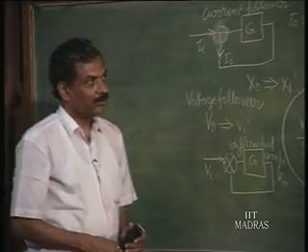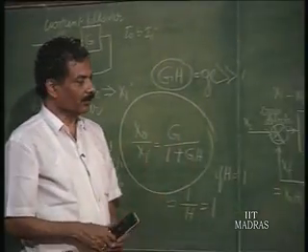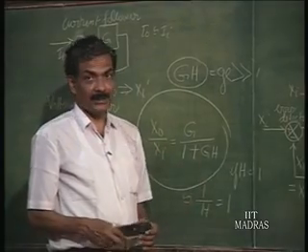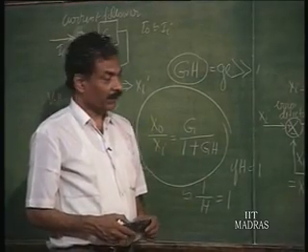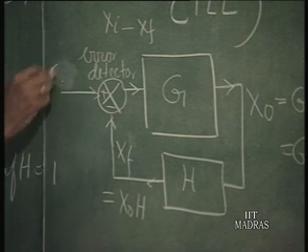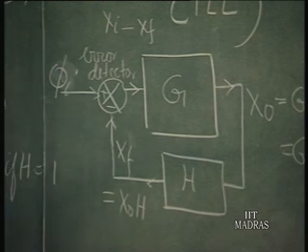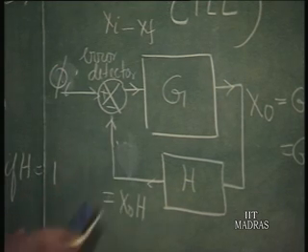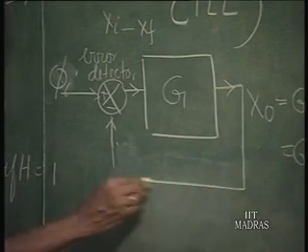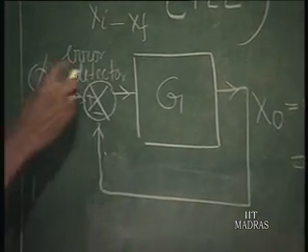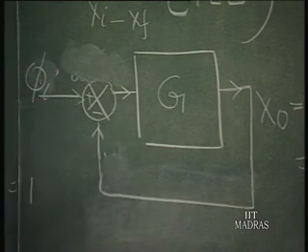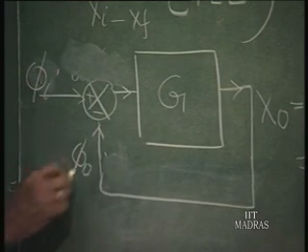Now, when we go to phase lock loop, neither voltage nor current is going to be the considered input here. What is going to be considered input here is nothing but phase. Let us say we will put this whole thing H equal to 1. This is not going to be an error detector, it will be called, this is phi I and phi naught.